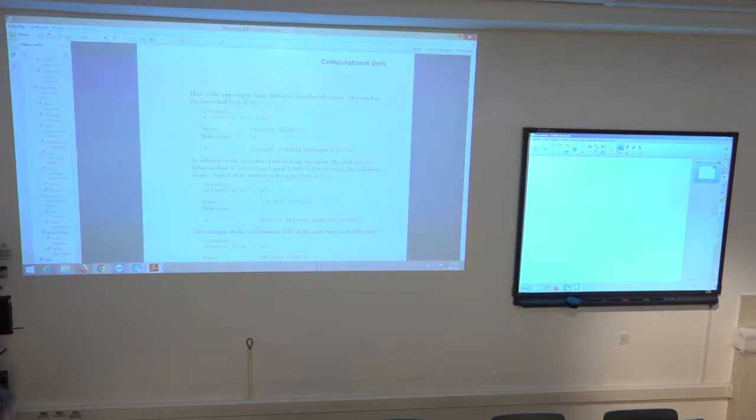Sorry, this is a logical shift of the shifter input by 5 positions, relatively low. So it takes this value from the input register, places it over the lower output word, and then shifts by 5, which means 5 positions to the left.